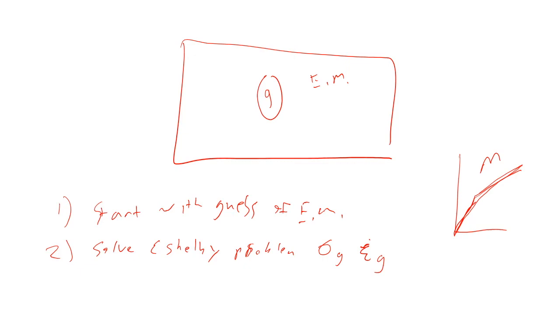Okay, so now we've got a guess of the stress and the strain rate in each grain, and we have a guess of the effective medium. We use all of the grains, average them together to get new properties for the effective medium, solve for the grain stresses and strain rates again, and plug it back in until it converges. And then we go to the next strain increment, and we do this for each strain increment.